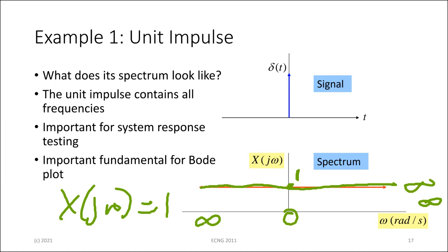It's like you're sitting down with a signal generator on the input of the system, and you start at low frequencies and send in all the frequencies, as high as the signal generator can go and beyond. So the system is subjected to the frequency content of an impulse.